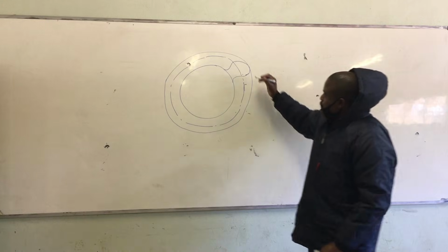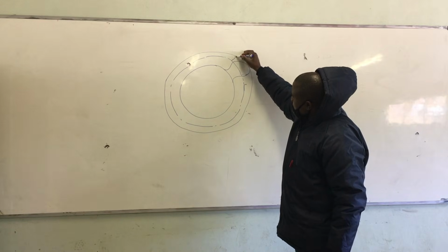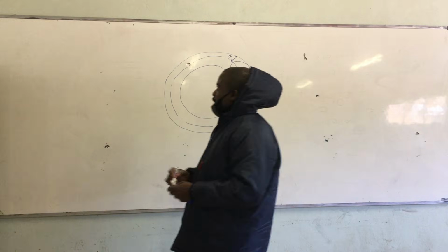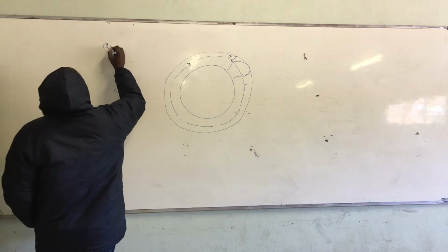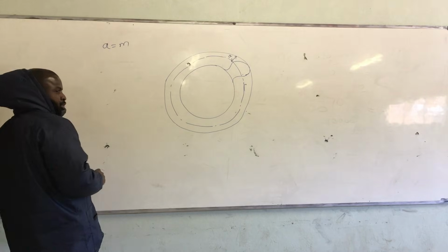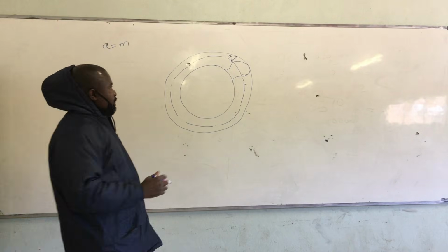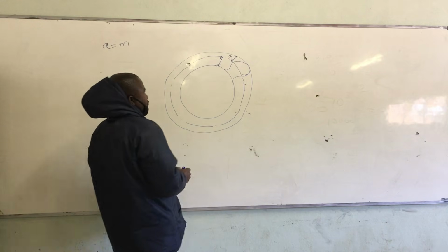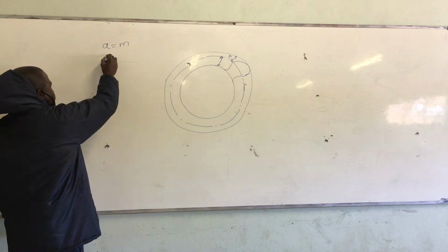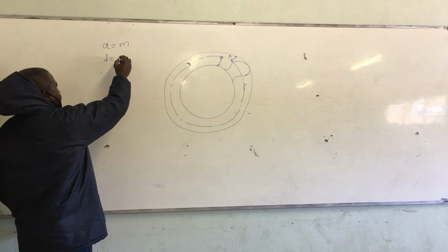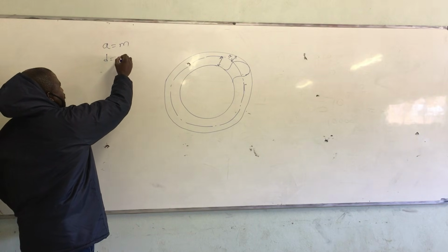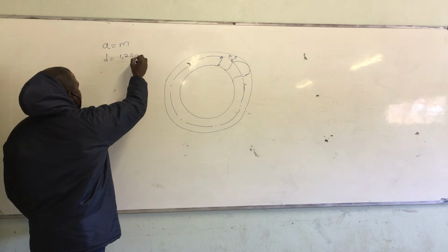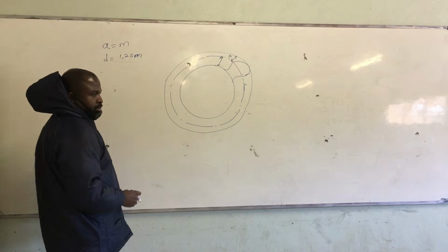So this one, it will be your addendum. Addendum, which is the same as module. So this one, it will be your dedendum. Dedendum, which is the same as 1.25 addendum or module.